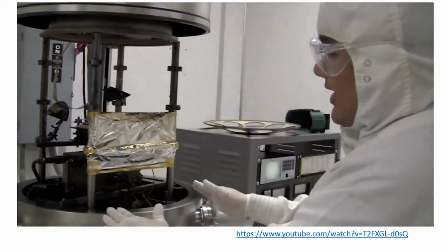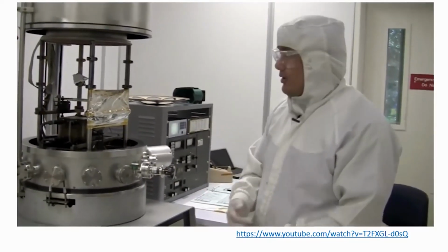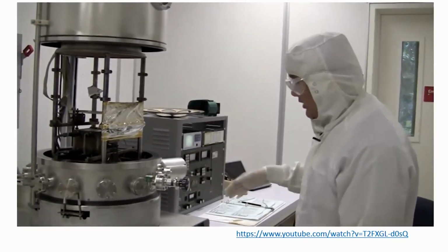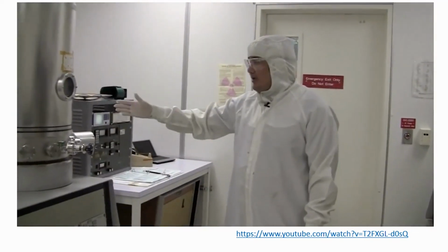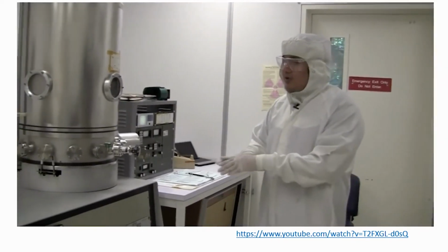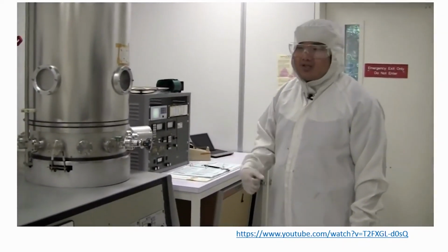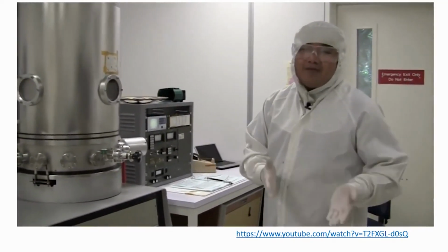We can bring this chamber down and put it back into high vacuum. So we're going to do that now, is we're going to lower the chamber. Now that we've closed the chamber, and our samples are in there, and our crucible is there, and the shutter is closed, we can begin the pump down process. So right now the system is in atmosphere, normal atmosphere. So we want to bring it down to the high vacuum.